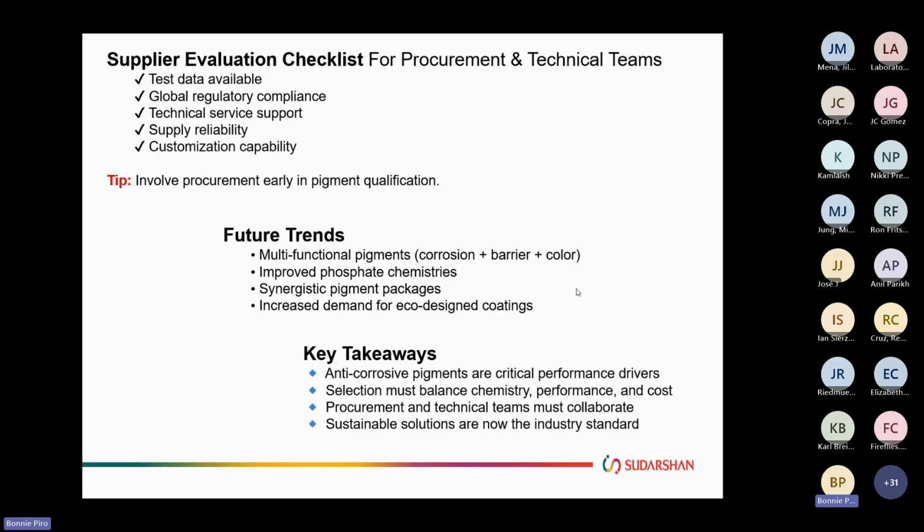You get the corrosion performance, barrier, and a lot of times we now start to see color being added into the undercoats to allow for a better value and use of your top coat. So if you have a similar color undercoat, you don't need as much film build of your top coat, and you can potentially help with your overall value and use for your system approach.